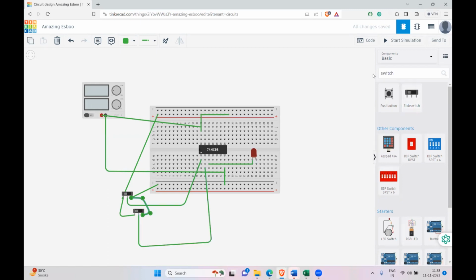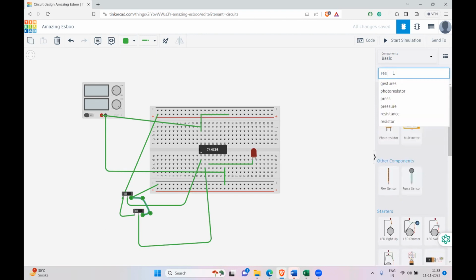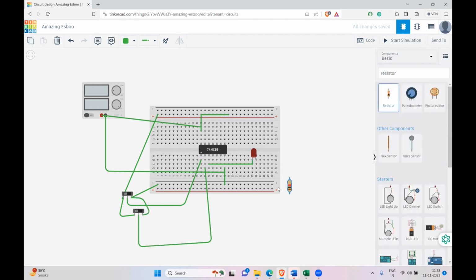Since an LED cannot be connected directly, you need a current-limiting resistor. So I need a resistor to protect it. I will place that resistor somewhere here. And now it is directly grounded, and the value of a resistor is generally in ohms. Typically 330 ohm is what you put. And some mistake is there because this is anode and cathode, and I want to flip it.